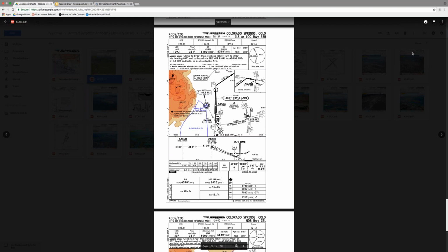Yeah, we aren't allowed to operate. Like you saw there, it said minimums, and you can even hear the captain say decision to land or something like that. Basically, if he can't see the approach lights when it says minimums, he can't see where the runway is going to be, then he'll execute what we call a go around, where he'll throttle up the engines and go missed on the approach because it's unsafe to land at that point. He has to have that visual indicator when he reaches that decision height.